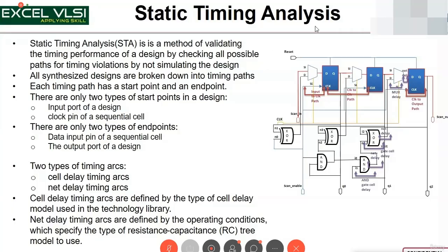within one clock domain. STA is performed only within one clock domain. You have a design with this one clock domain, this one clock domain separately. This it will analyze, this it will analyze. So passing any signal from one clock domain to the other clock domain, static timing analysis will not check. That's a limitation of the STA tool. That's where we use other tools like CDC, the clock domain crossing tool. So all those we will do.